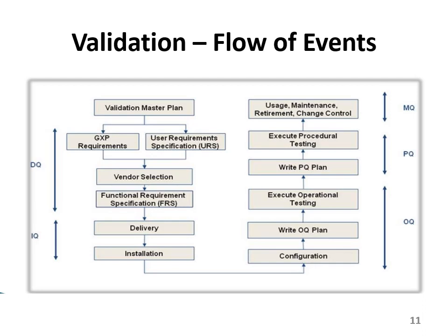Execute operational testing. Now you have written the operational qualification plan, and now test it: is it working? If it is working, excellent. If it's not working, you need some changes, do the changes. Then the performance qualification, PQ, write the PQ plan, how to perform on the machine. Execute procedural testing, then again test it.